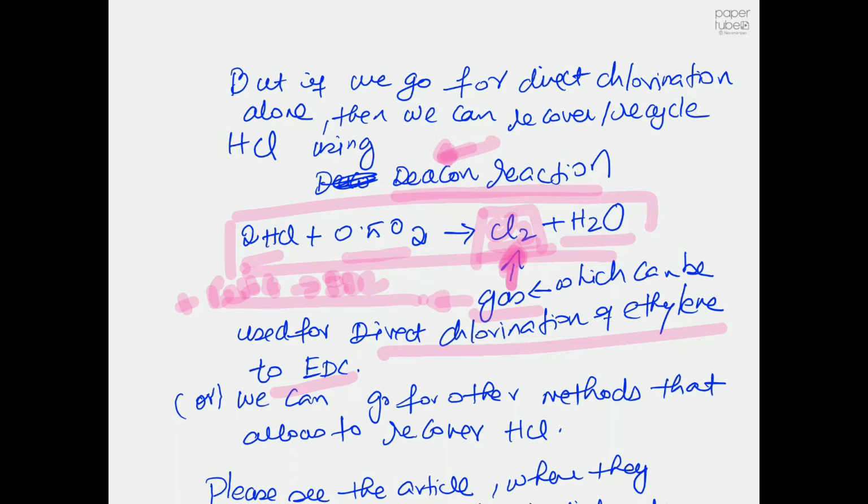Why are we talking about all these processes? Before touching the software, as I said, we need the full reaction stoichiometry, and we also need to think about the other ways to deal with this design project. For example, I can remove the third step, which is oxychlorination of ethylene to ethylene dichloride, and replace it with the Deacon reaction. It will also make the process more efficient.